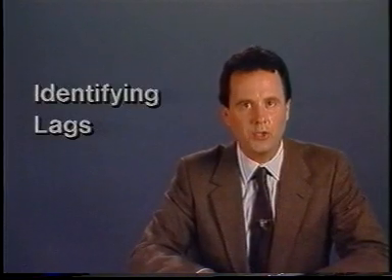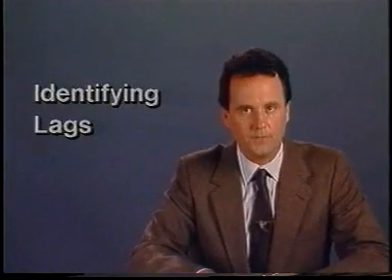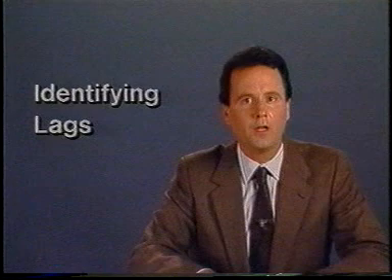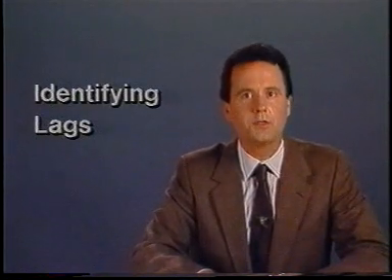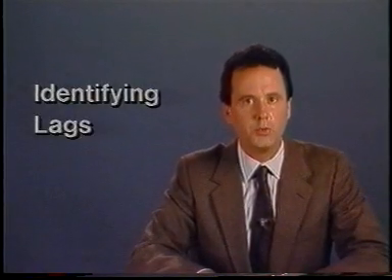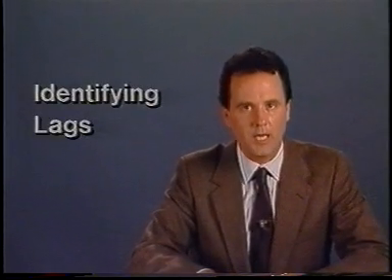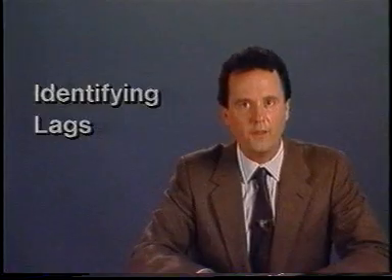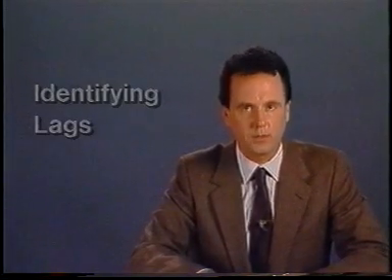In order to achieve loop stability and responsiveness, it is important to identify and measure all the lags in the loop, including the process itself. The reason for this is that if the largest, which is to say the slowest, lag is too close in length to the next slowest lag, it will be difficult to tune the loop to achieve stability. In other words, the slowest lag should be dominant or substantially slower than the next slowest lag, and by as wide a separation as possible.